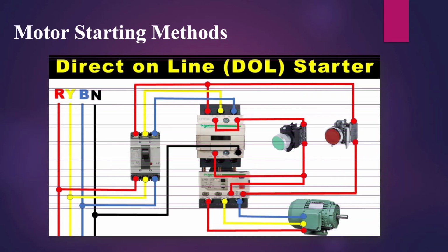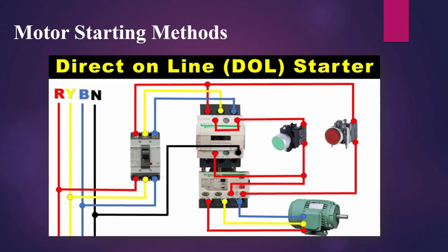Let's look at the question of how you start the motor. There are three options associated with starting a motor. They are direct online, star, and delta or soft starting. Direct online starting connects the motor stator windings directly to the mains supply. The motor will start and accelerate according to its natural characteristics. This starting method is suitable for stable supplies, mechanically stiff and well-designed shaft systems, and it is the most common starting method available on the market.